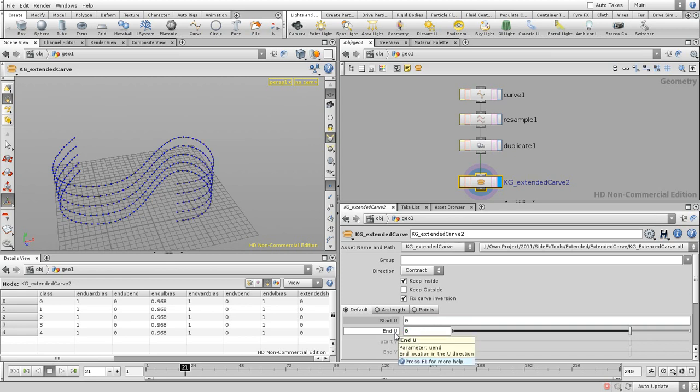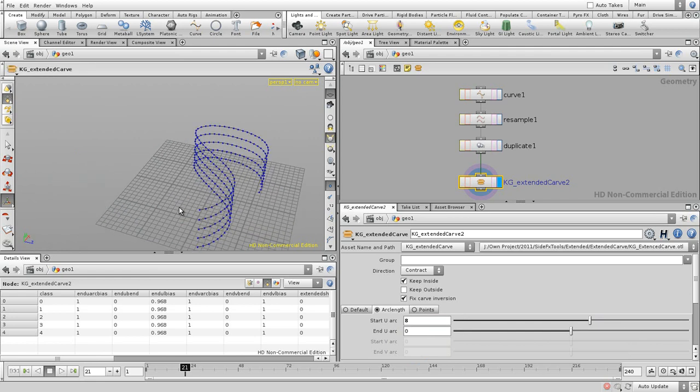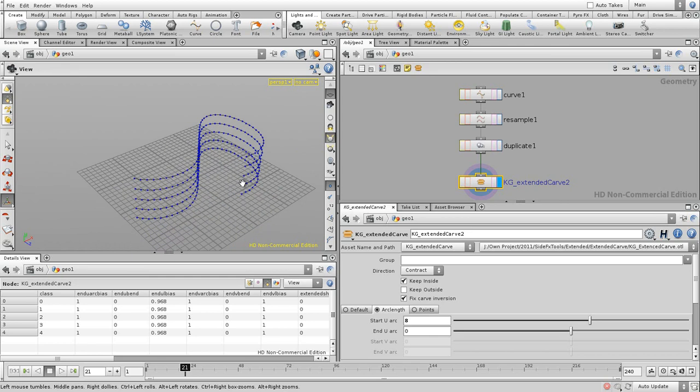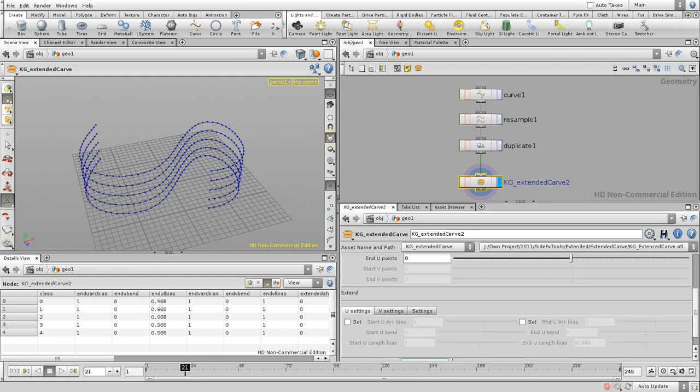to both 0 values. The other thing you can do is use arc length. So for example, if you want to chop something off using a length of 8, it's going to measure the arc length of these curves and remove a distance of 8 from the curves. Then you also have the ability to remove points, so it's going to count the points and each time a point is going to be removed. So these are the 3 options that you have.